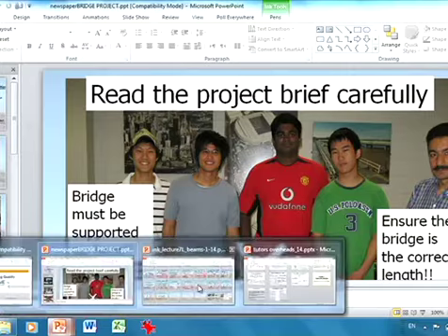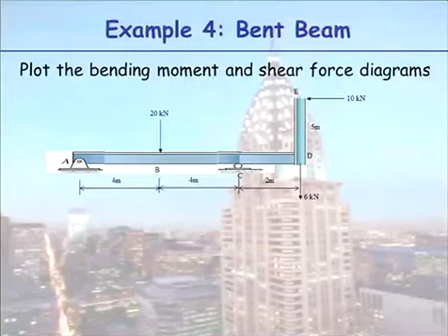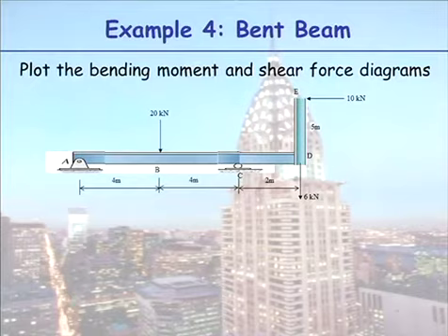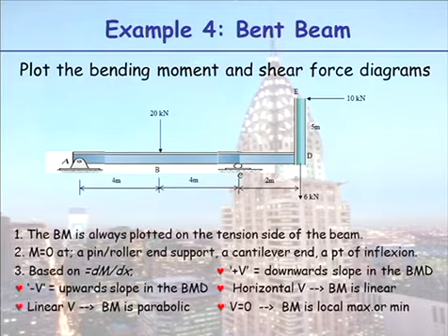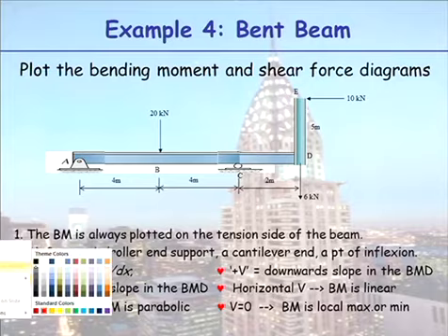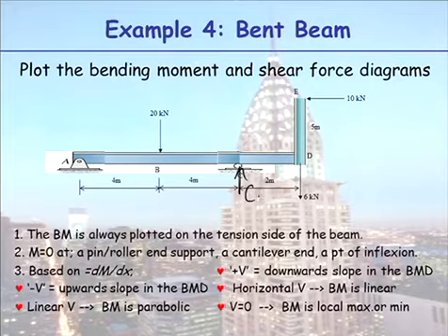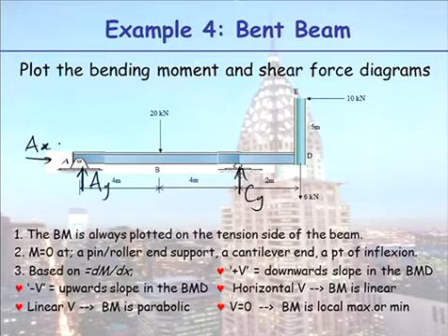So we're now going to go back to drawing that bending moment diagram. Before we draw this bending moment diagram, we of course need to know our reactions. We have a CY force here, AY, AX. Where am I going to take moments? Where's the best place? At A. Do people say at A? Oh, you can take it at A or at C. I'd take it at A.